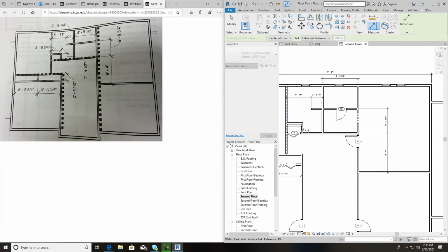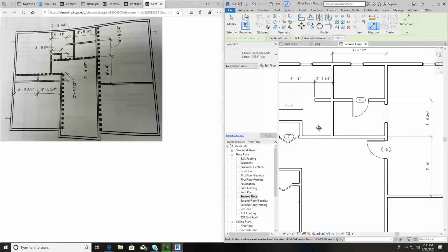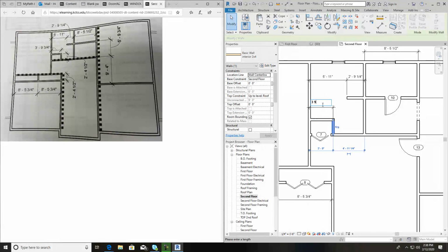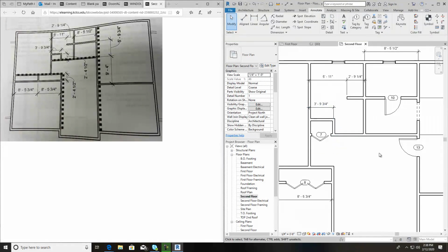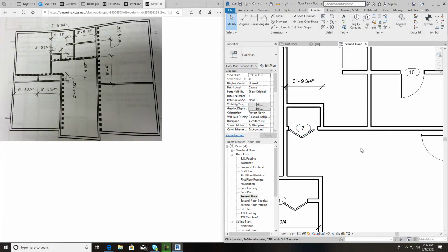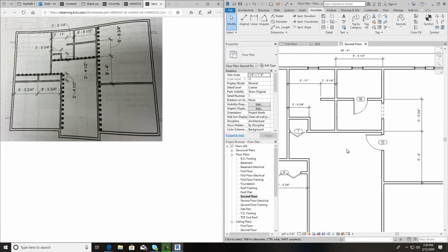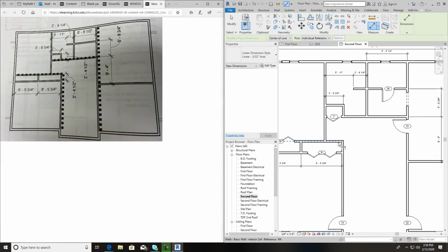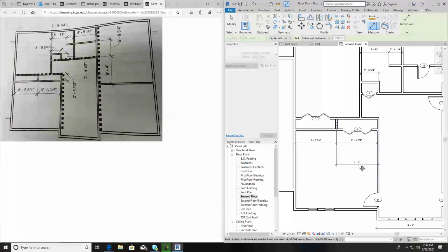This one from there to there is 3 foot. Should be 9 3/4. So I click on that, 3 foot 9 point, and I could put 0.75 or put 3 divided by 4. Then you might have to center this up a little bit better. Now, the next one that we're going to do is we're going to measure this from here to here. 2 foot 4 1/2 is perfect. Measure it from there to there. 8 foot. 8 foot 8.